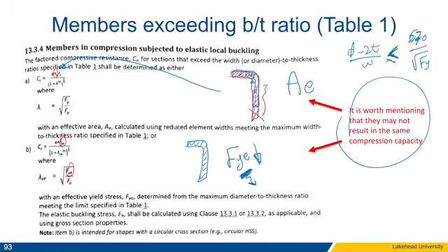So one of the ways is to consider this depth as an unknown and assume the yield, assume the 670, and we know the W, and you will have a smaller depth, and that will be the one that will dictate the smaller area. Or we will say, you know what, let's just keep the cross-section as is, and consider the F yield to be a reduced F yield. So you will consider this to be unknown.